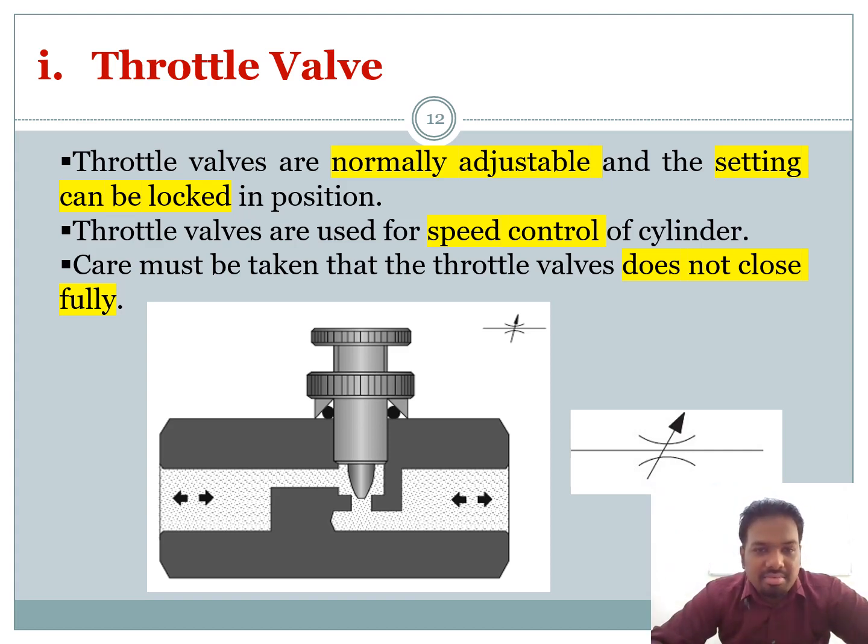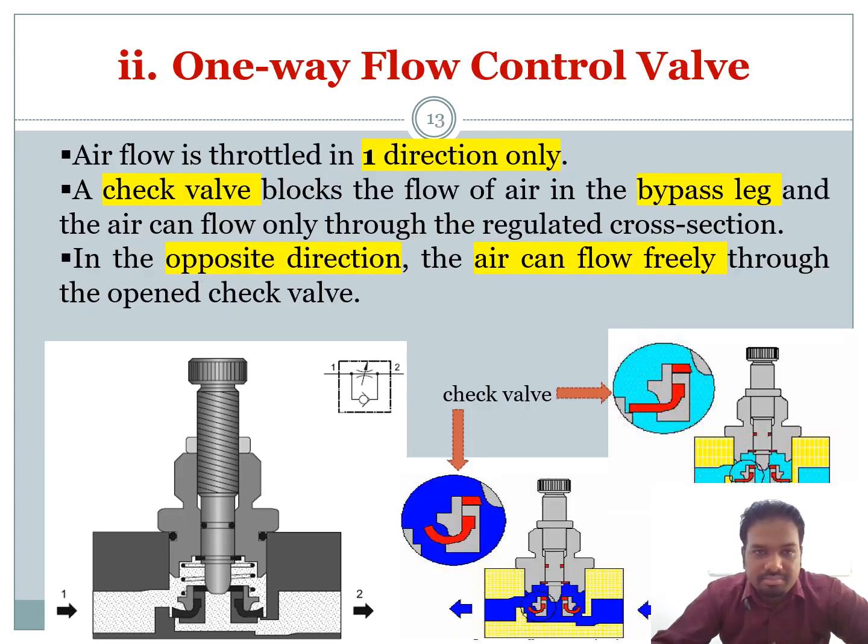Okay. Care must be taken that the throttle valve does not close fully. If you close fully, no flow will be available and your cylinder cannot be extended, and it can cause damage to your system. Okay, so this is the symbol of the throttle valve.